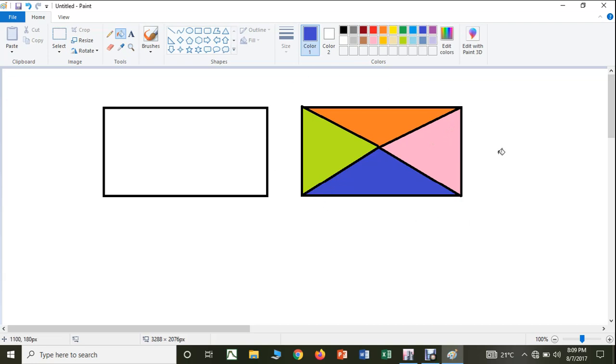This is possible when you have a one-way slab. This type of loading occurs when you have a one-way slab. When you are doing the manual design, for example, if you are manually designing a beam, you are supposed to consider the loadings like this. You have to calculate the area of this. After calculating the area, you convert it to per meter,